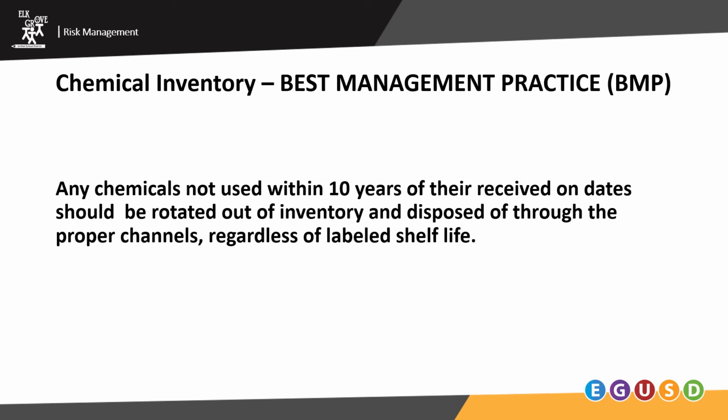Best management practice: any chemicals not used within 10 years of their received on dates should be rotated out of inventory and disposed of through the proper channels, regardless of labeled shelf life.